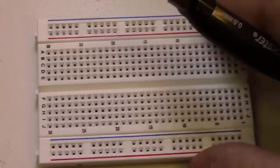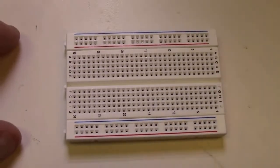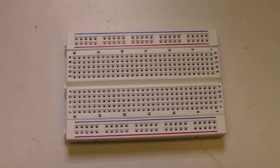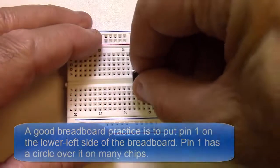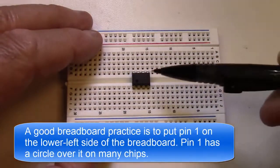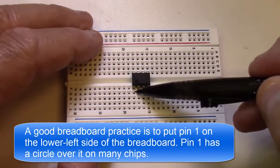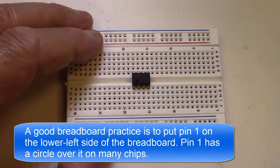So let's go ahead and get started. So here's my breadboard. I'm going to back up a little bit, and the first thing I'm going to do is put the chip down on the board. I like to put the chips on the breadboard with pin 1 on the left downward side of the chip, so the lower left.